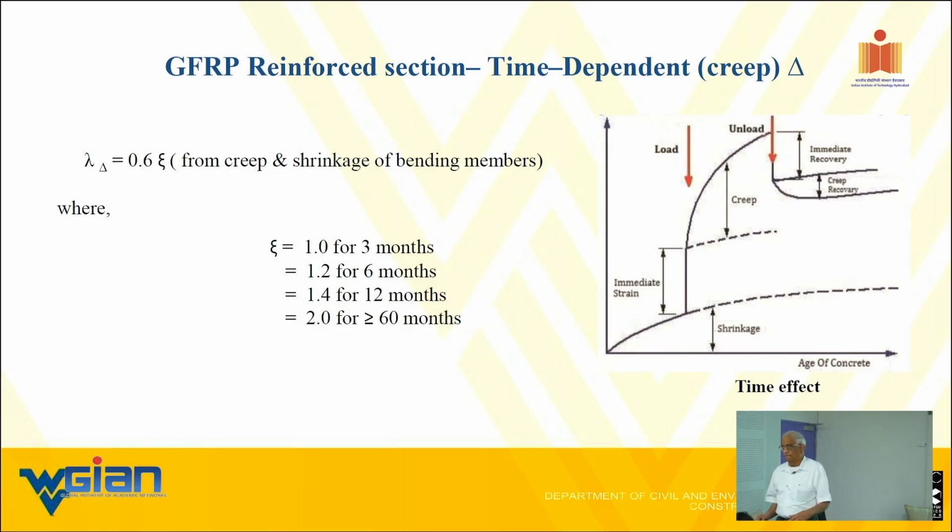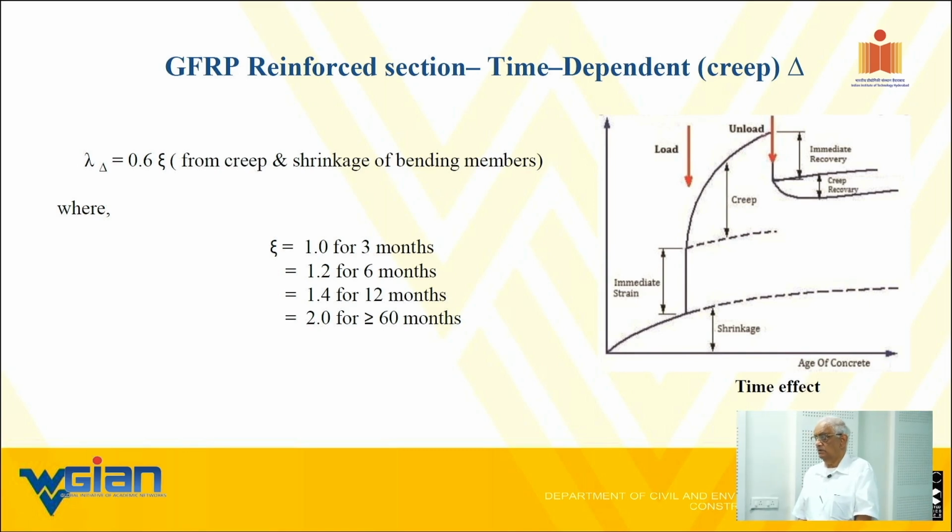It is said that creep doesn't start until the load acts on the structure. Creep doesn't start till you remove the shoring. It only starts after you remove the support condition.